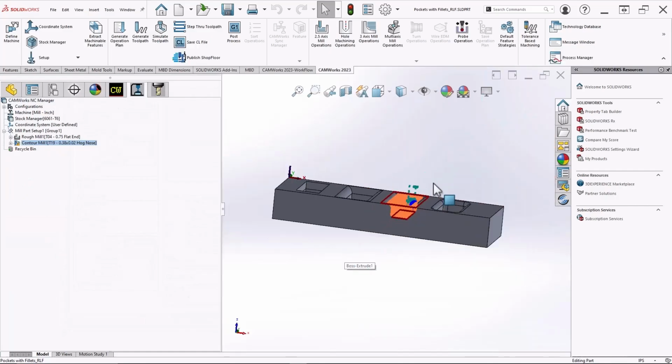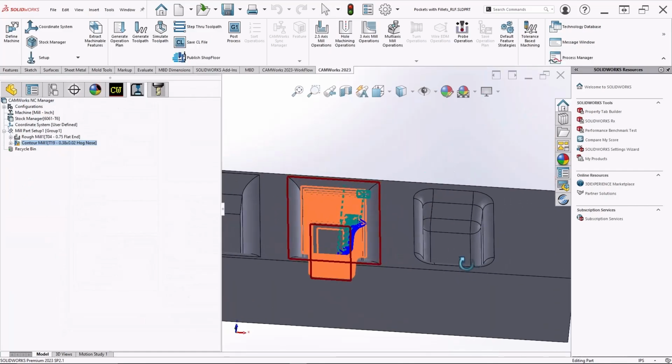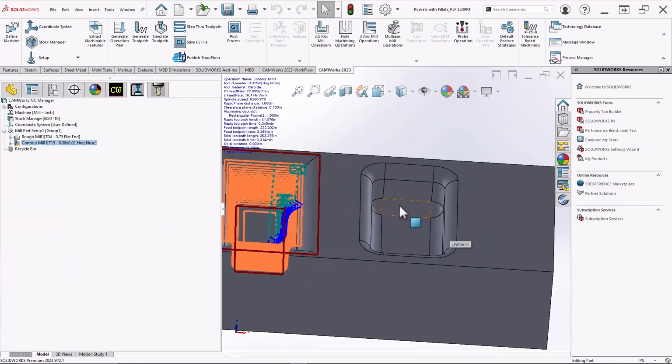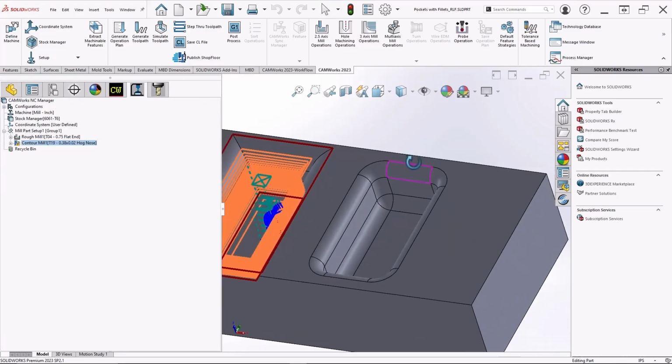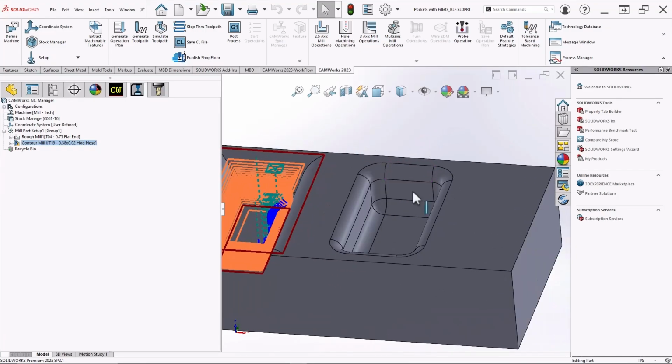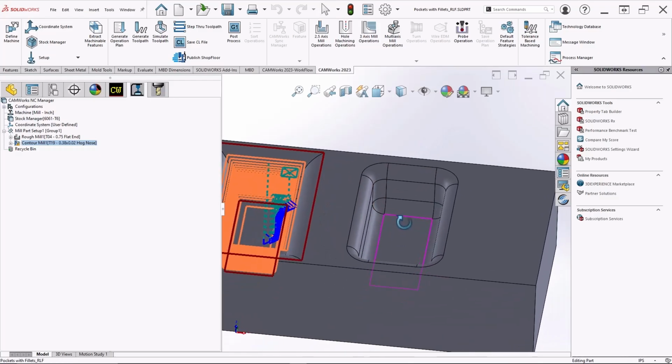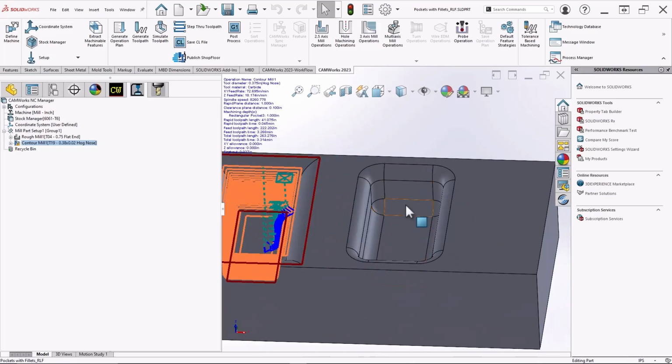All right. Now this fourth example here, because you have fillets in the corners, you do not want to recognize this as a 2.5 axis feature. And in fact, it won't recognize it correctly. This would be an example of a multi-surface feature. So this type of pocket, you're going to want to recognize it as a multi-surface feature.